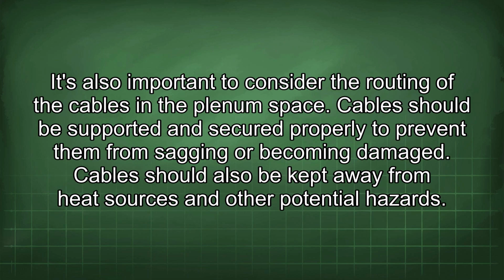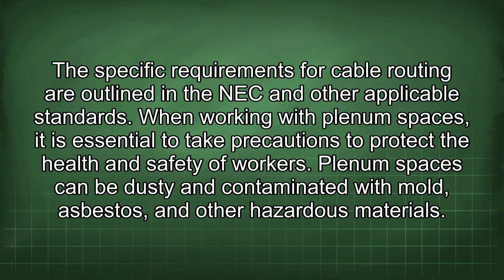It's also important to consider the routing of the cables in the plenum space. Cables should be supported and secured properly to prevent them from sagging or becoming damaged. Cables should also be kept away from heat sources and other potential hazards. The specific requirements for cable routing are outlined in the NEC and other applicable standards.